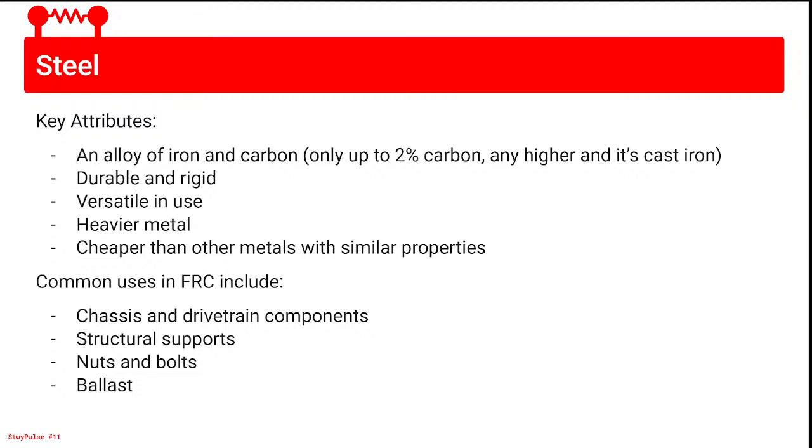Robot was a 2019 robot 694 made. It was very front heavy, not equally balanced whatsoever. So we had to add a little bit more weight to the back. Later on, if you want to come up to speed, there are two plates in the back over here. Both of those are about 3 to 5 pounds of steel. So we just added that onto the back, slapped it on, just trying to even out the weight distribution a little bit more.